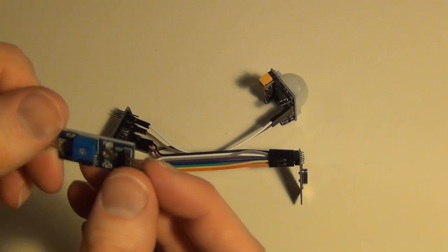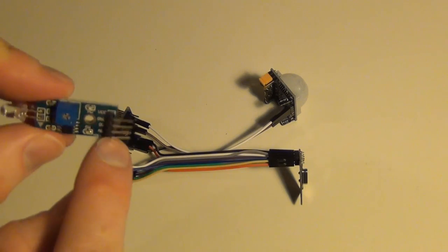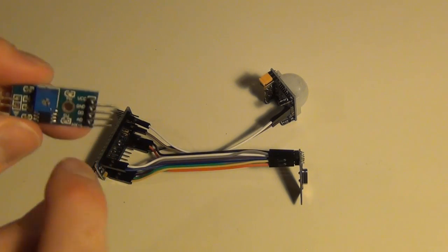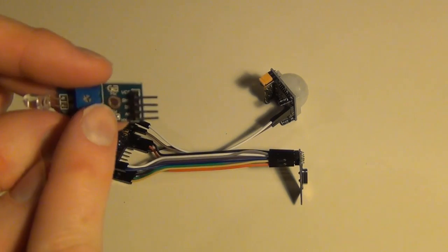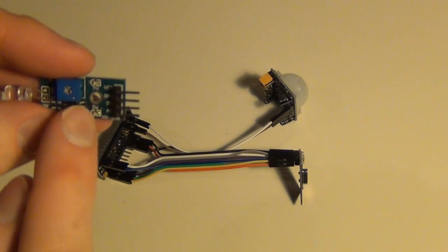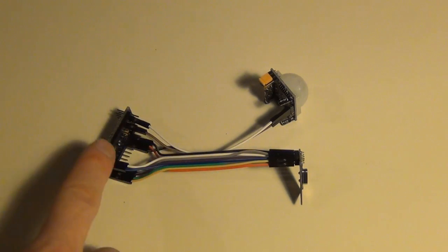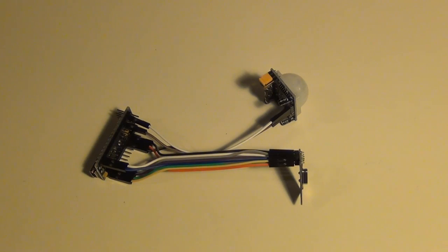Another common mistake I seem to make is not checking where my connections are actually going, or not double checking, triple checking. So I might swap VCC for ground either on my sensor or maybe on my Arduino. So just make sure you watch out for that. Make sure you supply it with the right power it needs, and then your connections are actually wired in correctly.